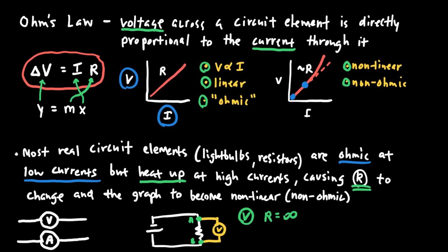So let's think about what that might mean and why that matters when I'm making measurements of voltage. If I attach the voltmeter there and it had zero resistance, then all of the charge would immediately flow around the resistor through the voltmeter back to the battery. That would create a short circuit, which can cause the battery to run out of usable energy very quickly. If it had some normal amount of resistance, then there would be essentially two resistors in parallel. The equivalent resistance would be different, the current in the circuit would be different, and it would manipulate the thing that I'm measuring.